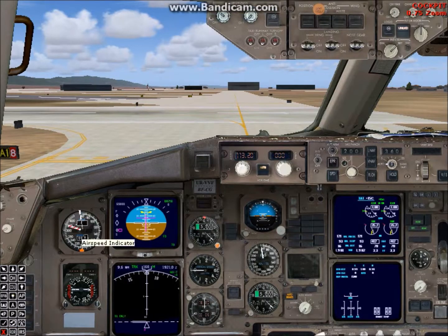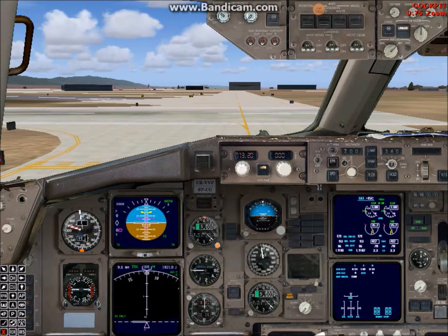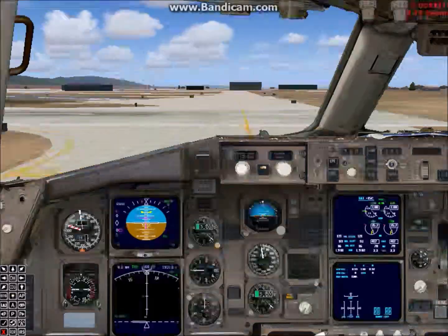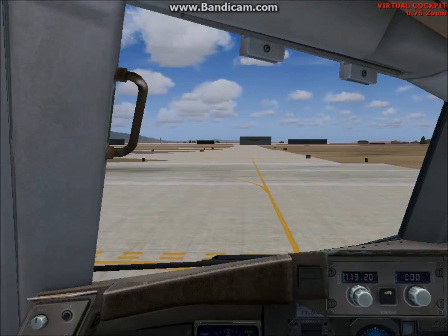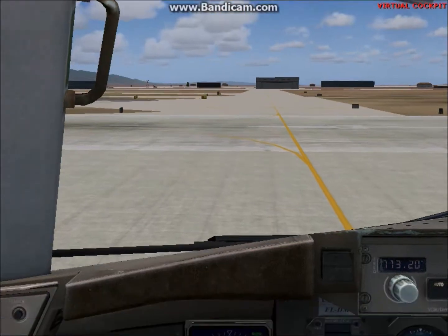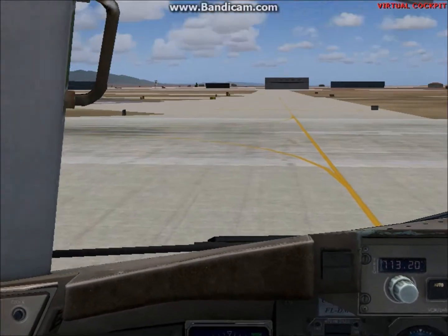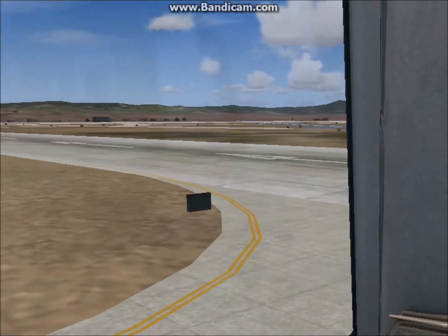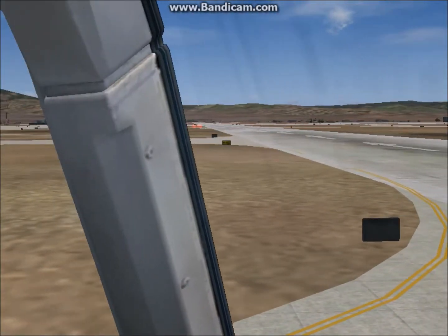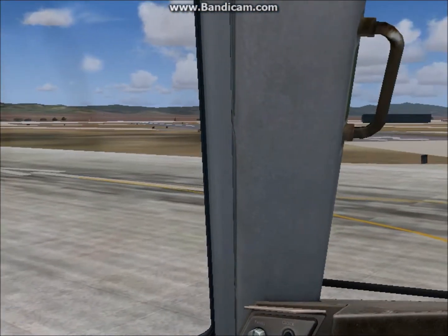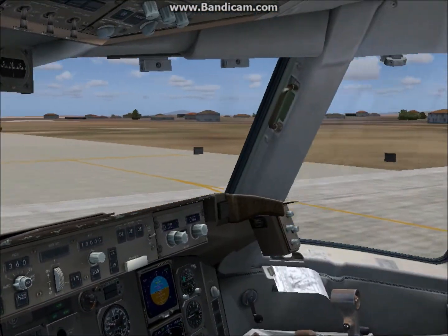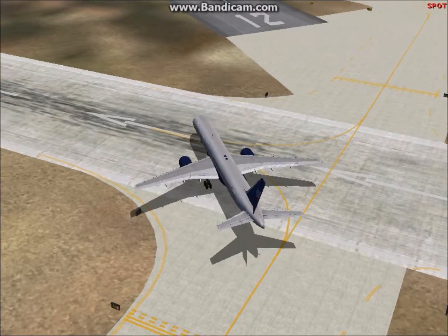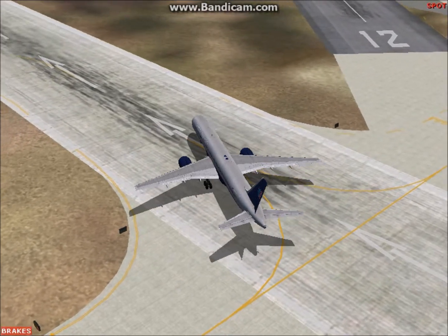directly to your next waypoint on your route, after the route discontinuity, click the line selector key, then the line selector key at the route discontinuity. This will allow you to go direct. If you need to go via a jet or Victor airway, type this, then hit the line select key for the via, which is just below the route discontinuity. And then click the route selector key and have it go to that waypoint.